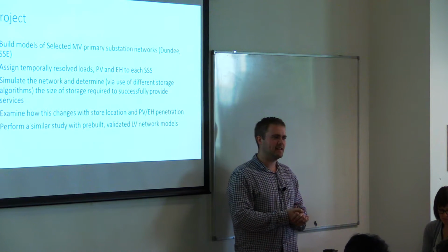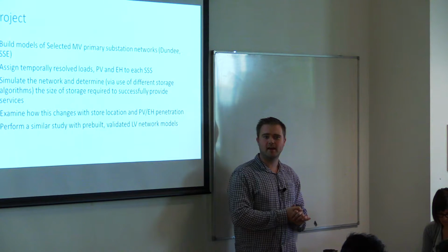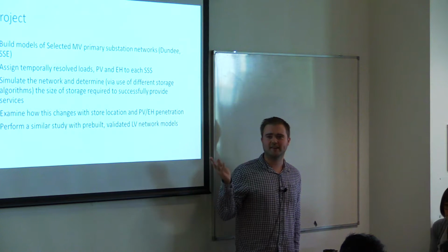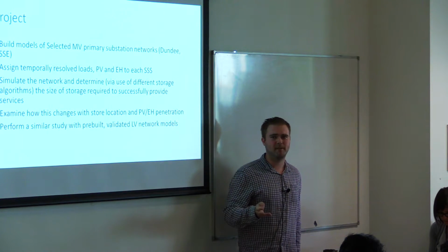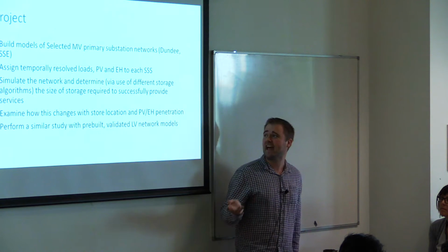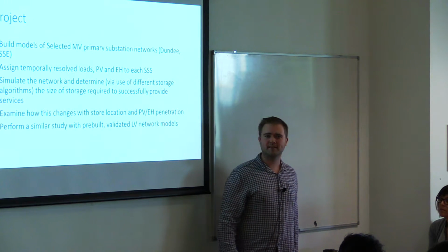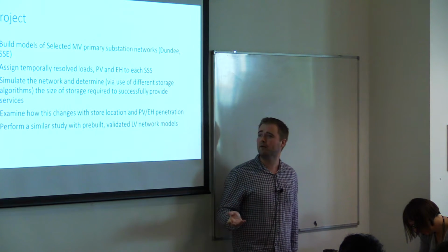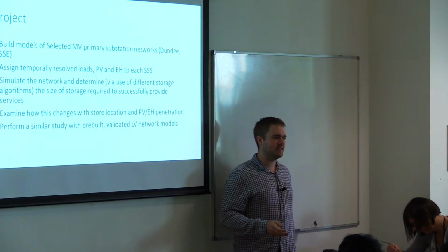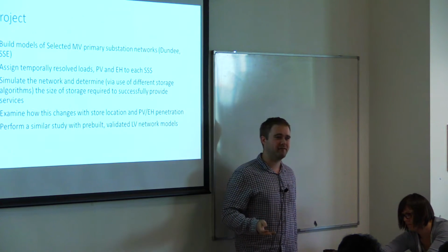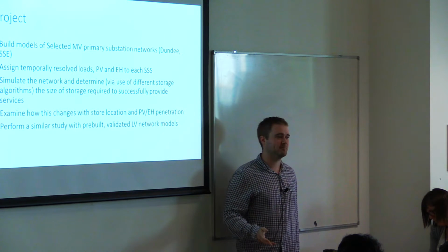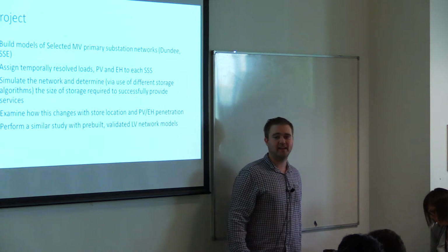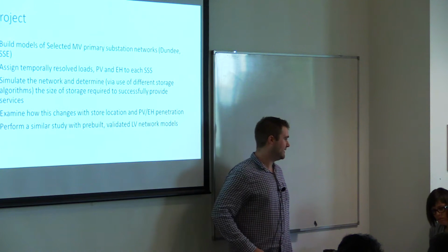I'm going to be assigning load profiles based on CREST type modeling simulation. I've got real weather data for PV and electric heat pump simulations, which I can use to build up demand profiles for substations and houses and such. I'll then simulate the network, see what problems we have with voltages, thermal violations, reverse power flow, leveling, and then add storage in various amounts to see how that affects the quantity required to provide these services, and see how this changes with different amounts of PV and electric heat. So that's pretty much the lot for me.